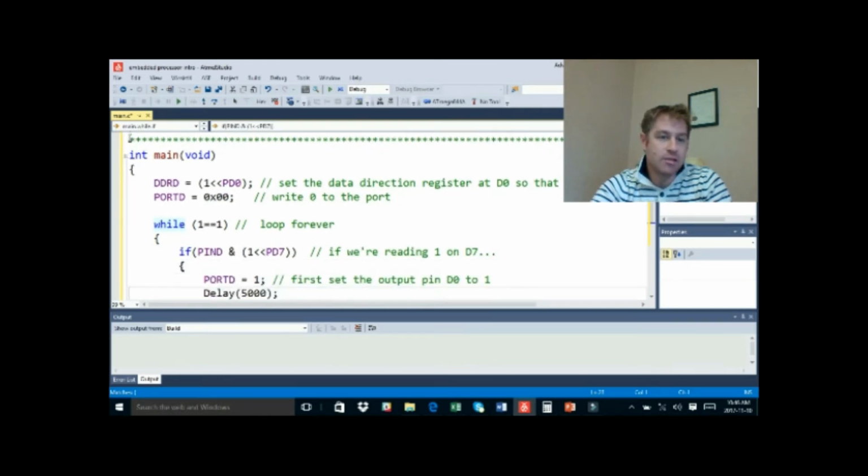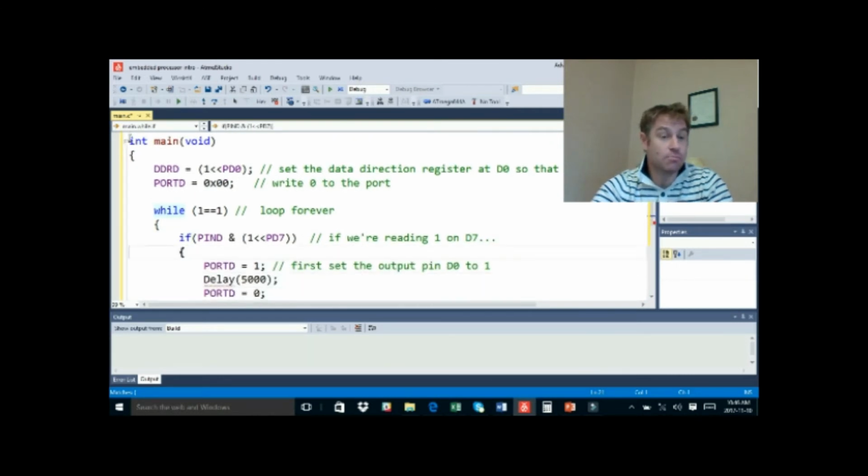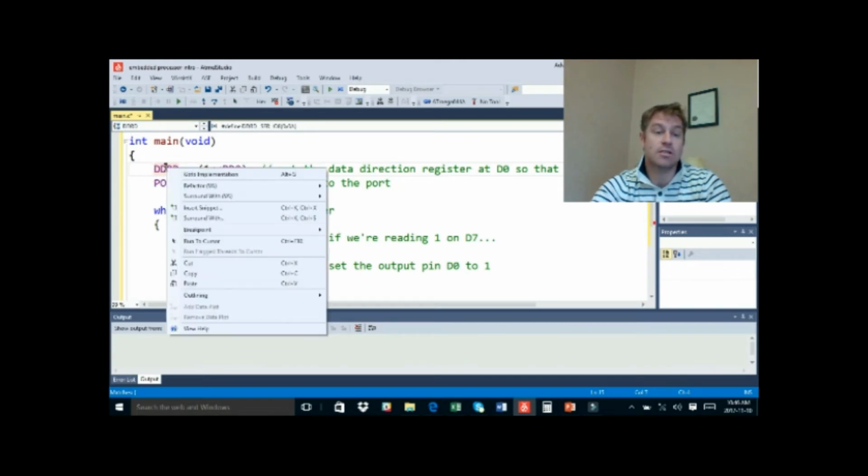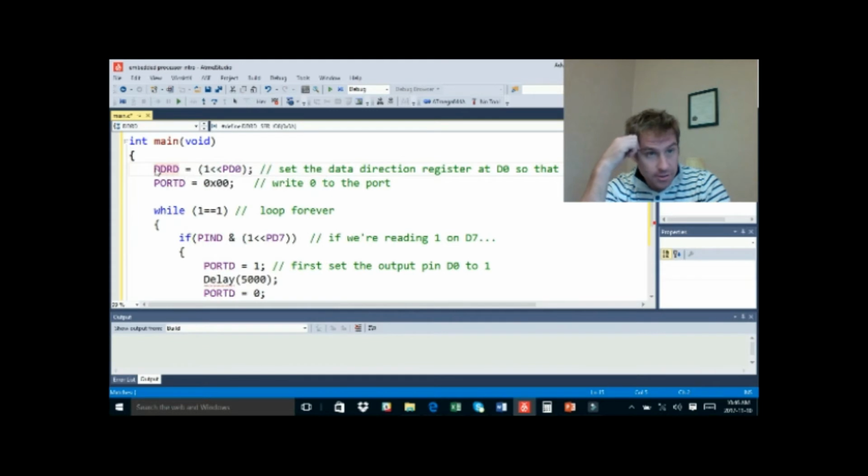In this main file, there are some variables that have appeared, and it's funny because this is certainly a syntax that you haven't seen before, because it's syntax that is used in embedded processors. So I don't think that most of you will have seen this type of syntax. So where do you think this variable DDRD is defined? Every variable that exists in a program must be defined somewhere. So they're defined in the ATMega library somewhere in their files.